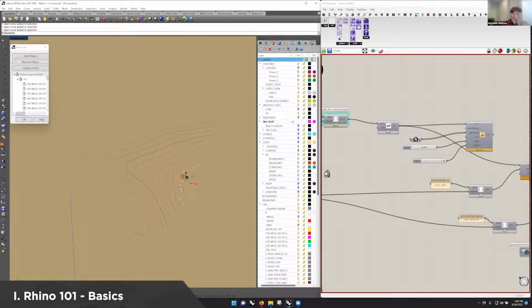If you select a contour and click the blue arrow, you can type in a value that will be related to units in Rhino. Currently we're in feet, so if I type in 40, it will raise that 40 feet. Then I can go to this one and raise it 39 feet and 38 feet, and you can get all of your contours to match up perfectly according to how you need to.